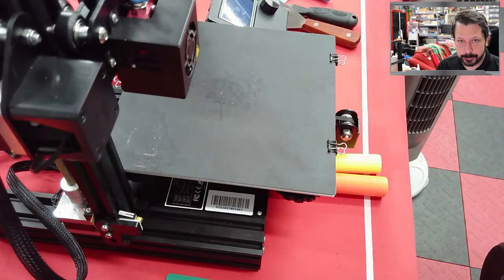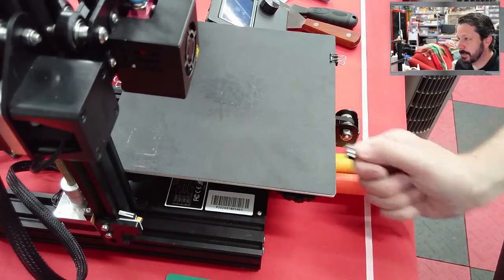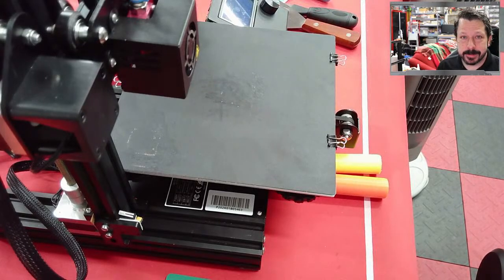If neither of those work, there are options for if it's possible to remove the print surface, like it has the bed clips and you can remove the print surface, then put that thing in the freezer for 10 minutes and let it get really cold, and sometimes that will pop it off of there. The reason that they're sticking usually is that you've printed too close to the bed.